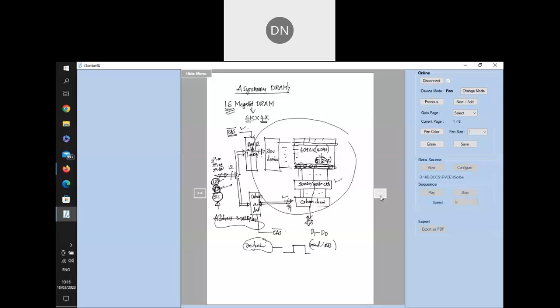You just have to enable the RAS signal and access the complete row. If you generate one pulse for RAS and enable a row, it's good enough, and refreshing will happen. You don't even need to read the data, just generate a RAS signal. These pulses have to be sent to all the rows, which means every row has to be selected.